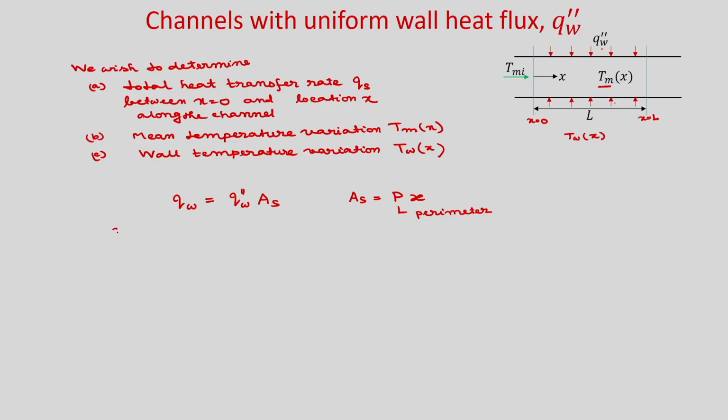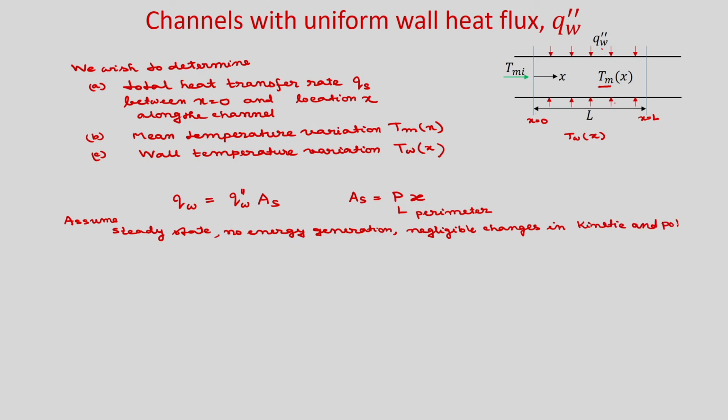So, we are assuming steady state, no energy generation, negligible changes in kinetic and potential energy, no axial heat conduction, and no viscous dissipation.